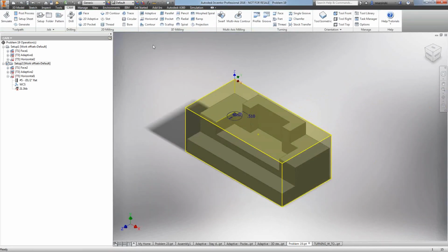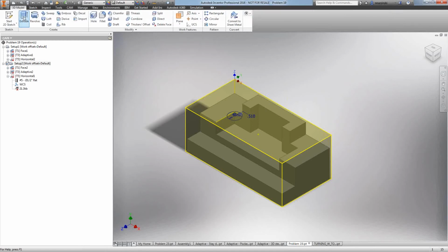Finish that. I can then come back to the Model tab and cut extrude that. So that's a cut, and I want to go to a selected face. I want to go to this face and check that. So now we've got some room for my end mill to come in and actually create clearance so that maybe something can slip down inside there.